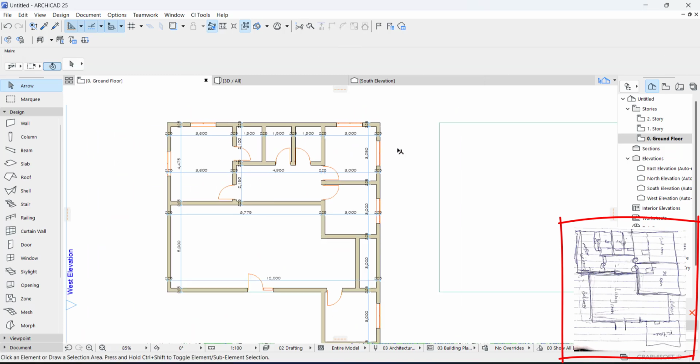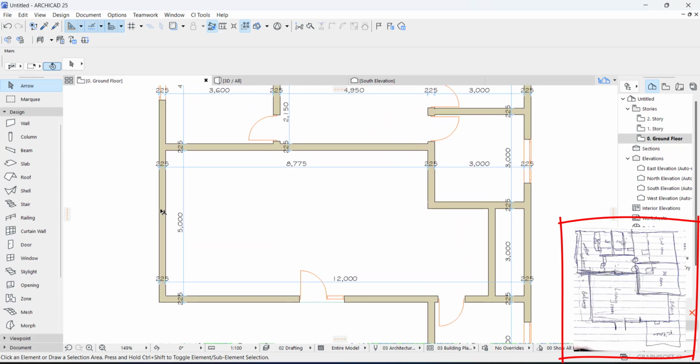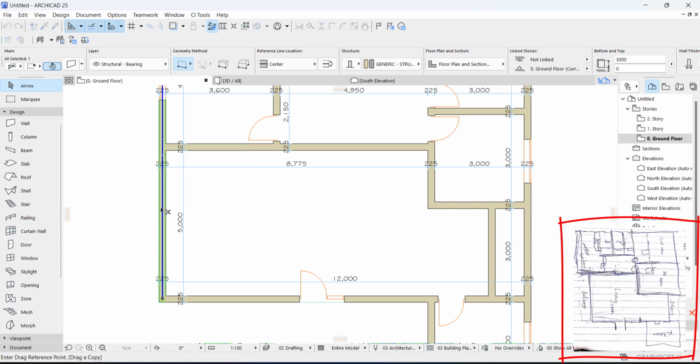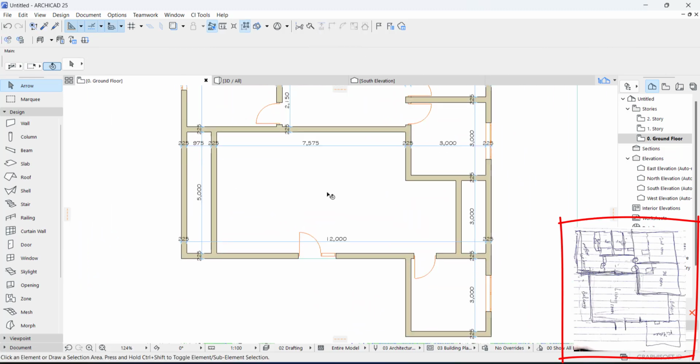Just pick and delete. Now we are going to open here. I'm going to show you how to create an opening, but let's do here. Do the same thing. Move a copy. Ctrl Shift D. 1 2. Cut. Okay, we have to create an opening here and an opening here, but before that, let's put a window.